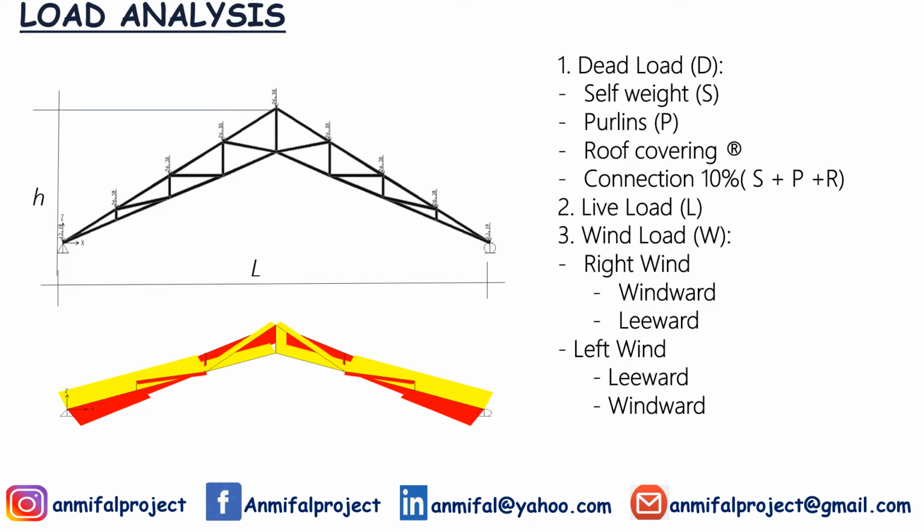There are many ways to find the member load analysis. We have the joint method, the section method, the Cremona method, or furthermore the direct stiffness method, which can be used for evaluating, analyzing, and calculating the member load. Structure analysis applications such as SAP2000 can be used for more complicated steel truss structure system analysis. Of course, they run by a numerical approach called finite element analysis.